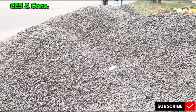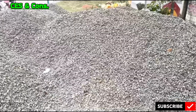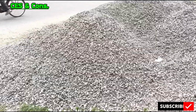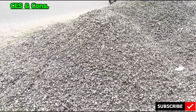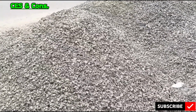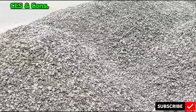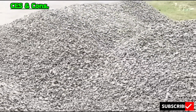This is coarse aggregate of concrete, that is stone chips. Quality of stone chips is a prime factor for making a good concrete. For concrete work, the selection and grading of stone chips is governed by IS 456-2000 and IS 383-2016. Aggregate should be graded as per Table 2 of IS 383-2016 to ensure a well-graded mix. Commonly used sizes are 20 mm, 12.5 mm and 10 mm depending on the structural element.